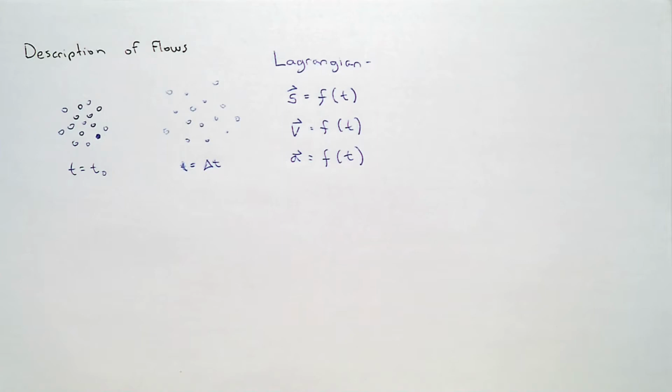The thing is that we're going to have to derive equations for each and every particle, right? And if we're studying a system with millions of particles, that means we're going to have to come up with millions of equations. Now, that doesn't seem like an efficient use of our time when we're modeling fluids. However, when we're studying systems where there are a very, very small number of particles, think of the air around a spaceship as it re-enters the atmosphere, the molecules of air are actually so separate that the number of particles is pretty much countable, and we can actually come up with good equations that describe the flow of those particles. In that case, the Lagrangian approach is a good approach.